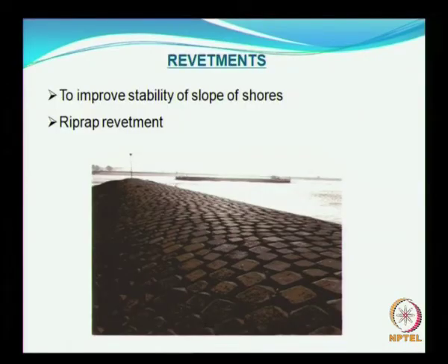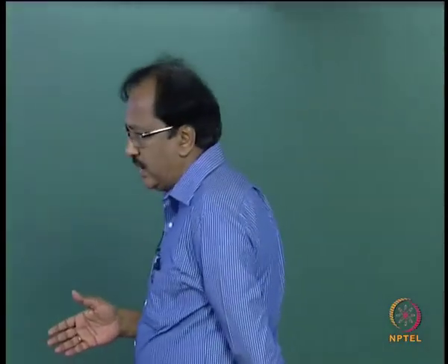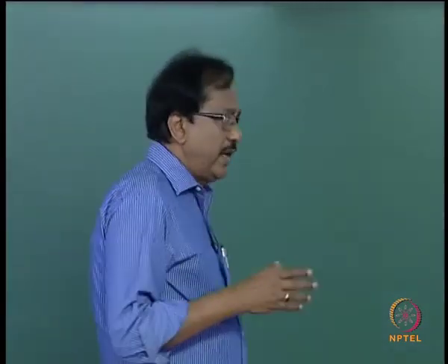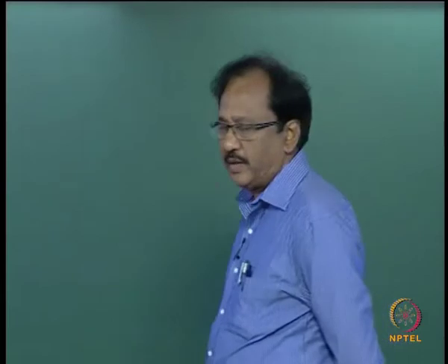Now what are revetments? Revetments are mainly to improve the stability of slopes. These revetments are mostly constructed along the banks, and sometimes it is also referred to as a revetment even if it is constructed along the coast, provided it is occasionally exposed to the wave action, maybe during a storm, an extreme event.